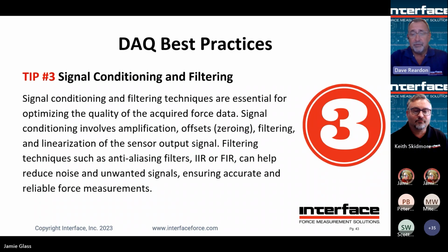Filtering, as I mentioned earlier, if you want to use infinite impulse response or finite impulse response or anti-aliasing filtering, all this will help assure that you get the best possible signal. And just as a mention, the BX8 that Keith mentioned earlier does have all these filtering capabilities within it.